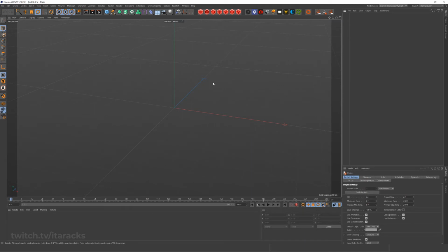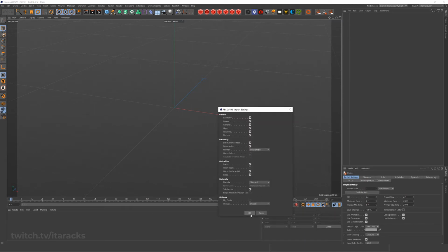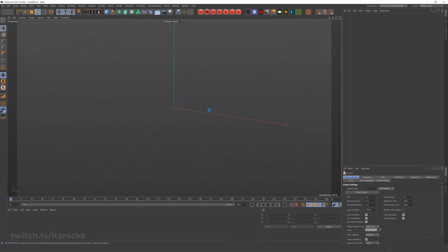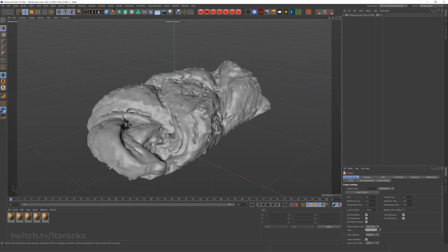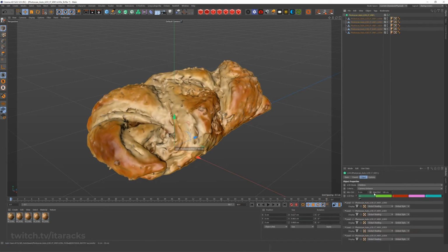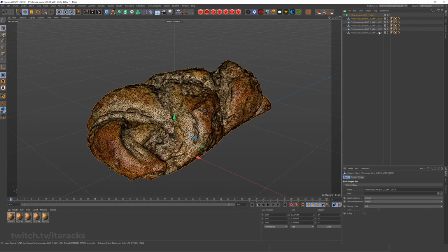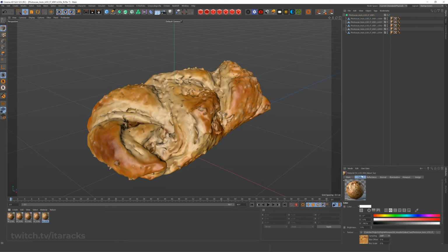So inside of Cinema here, for instance, if we go to open the tri, it's a single FBX, and it will take a little bit of time for Cinema to import it because it's running through all of the textures that were exported when this was done, all of the different objects, and adding them into Cinema's own level of detail manager, which is its own object that will nest all of these as children and give you all the functionality that you need out of that. And that's kind of where this entire idea was based. So we can see that it gave us this level of detail object manager with the controls here, and ordered all of our objects from highest detail to lowest detail. And it also imported the tri level of detail for baked text, and that's for all of these.